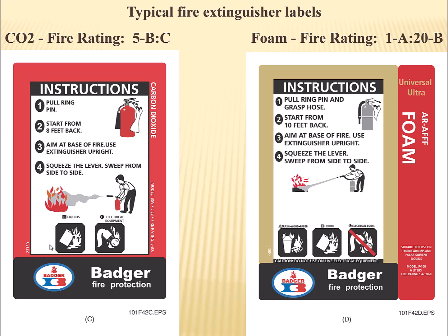It's rated for 1A and 20B, so it's good for both. It's mostly used on liquid fires, but if there are some ordinary combustibles in a Class A, it's okay. But what you cannot use, you see it's got a red line on the label flashing through the electrical equipment, because foam is just like water in that it's going to conduct back through to you. So you can't use a foam fire extinguisher on an electrical fire. So that's an important thing.